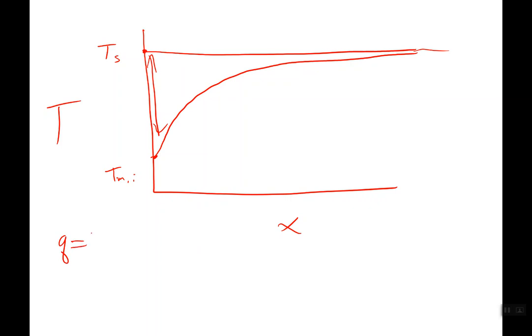All right, easy question. What's the general form of Newton's law of cooling? Okay, H times A times delta T. That's Newton's law of cooling, okay? So what we're going to get to is when you have a fluid that changes in temperature over some spatial dimension in your system, we're actually going to use this different form of Newton's law of cooling, which is going to say that Q is equal to H times A times delta T with a subscript LM. So that LM means log mean.